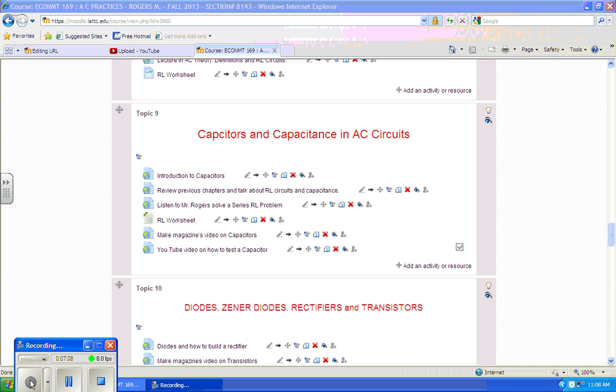And if you've calculated the current flow time period, you've just calculated an RC time constant. And we're using a really big resistor and a really big capacitor, a 1,000 microfarad capacitor. And the resistor is 1 meg ohm. How many is a meg? Kilo is 1,000. Mega is 1,000,000. So it's a 1,000,000 ohm resistor, right?